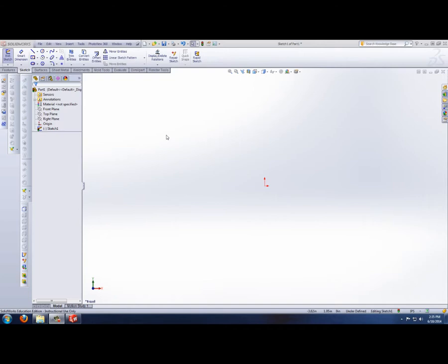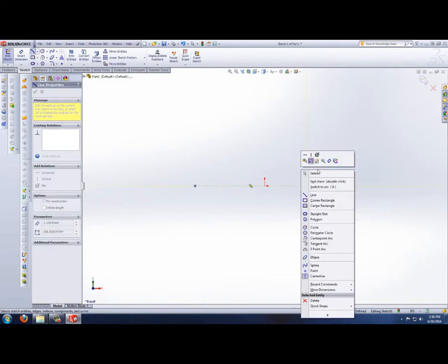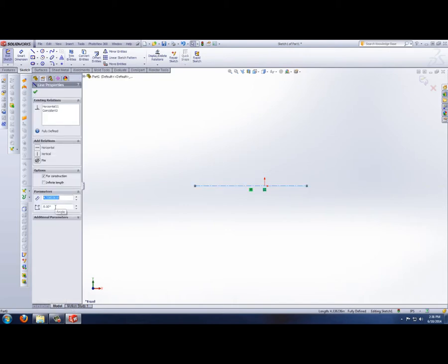Today I will be showing you how to evaluate the aerodynamic qualities of a part in FlowWorks. To do this, I am going to be using a simple hollow cylinder. To use FlowWorks, you need to have a part that has one interior chamber that is completely sealed from the outside.